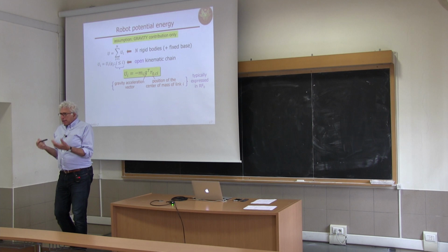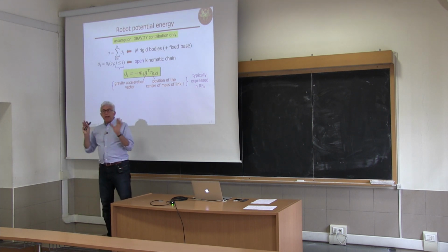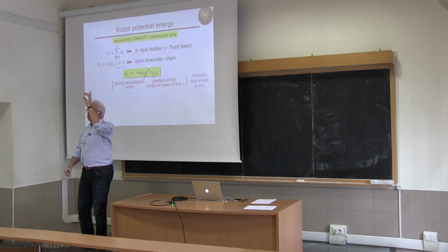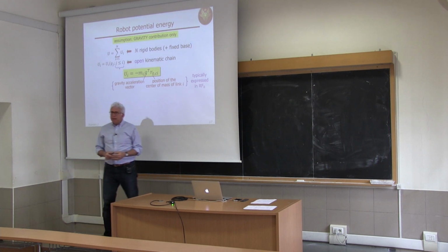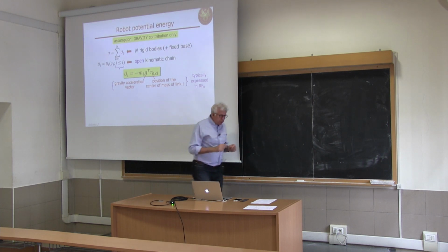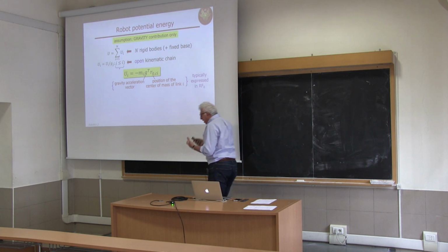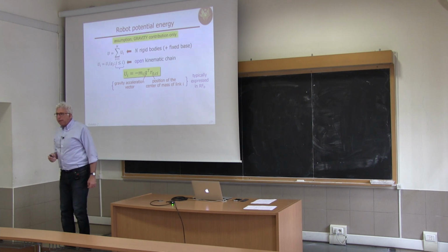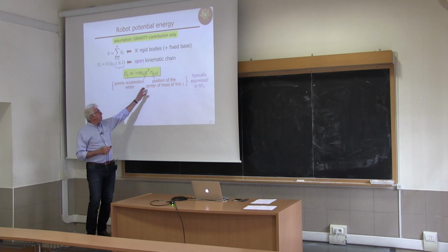In fact, in this way, you can take into account robots that can be mounted in any orientation of the base, so on the floor, on the ceiling, on a wall, on an inclined plane. This information can be coded into the software so that the actual acceleration of gravity, and thus the contribution of the gravity term to the dynamics of the model, can be adapted according to how you change the base. So this is very important and very useful.